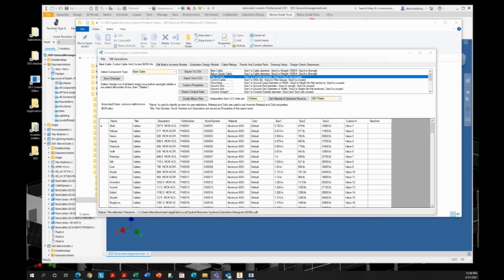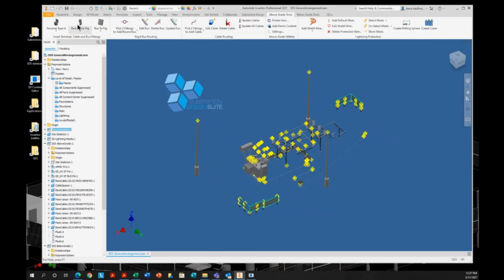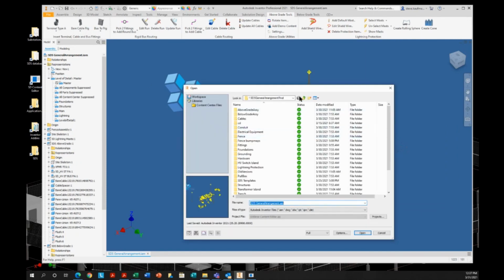Can the clearances be defaulted to phantoms? Not presently defaulted to phantoms. If this is a requirement or a request, if we get the consortium saying, hey, we want to see this more, I believe we could do something along that line. But until then, I'm just using the normal SDS methods to show this. You can also use the interference checks. I might have mentioned that already. If we use the interference checks, we can use that as well to look at both of these.